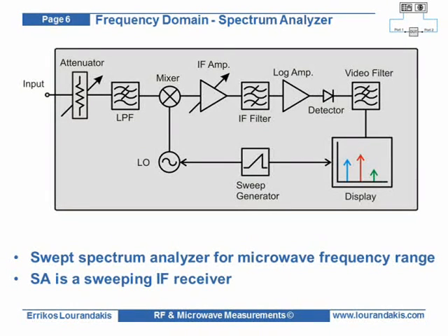The downconverted signal is leveled by an IF amplifier and filtered by a variable bandpass filter, which determines the resolution bandwidth of the spectrum analyzer. A logarithmic amplifier is following, and at the power detector, the envelope of the signal is captured. The detector output is passed through a low-pass filter, also called video filter, smoothing the signal before it gets displayed.